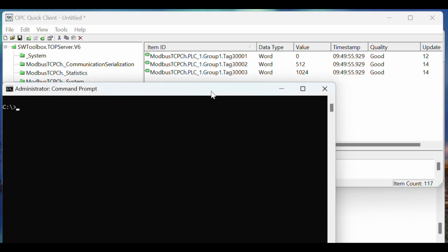In this last section, I just want to show you how we can verify that no other communication is possible even though the ModbusTCP communication has been established. For this example, I'm going to be utilizing a simple ping command from the TOP Server, which is node 192.168.1.2, to the PLC, which is on 192.168.1.3.